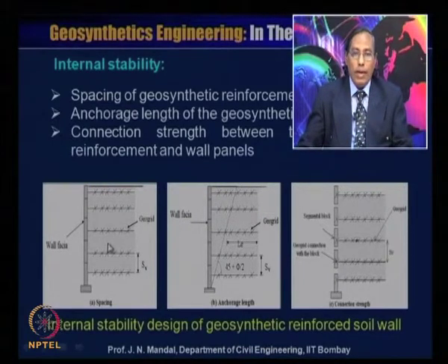If this is the wall, you need to know the spacing between the two reinforcements. This you have to design for internal stability of a geosynthetic reinforced soil wall. You should also require the length of the reinforcement, so you have to calculate the anchorage length. If you know the anchorage length of the reinforcement, then you can determine the total length of the reinforcement.